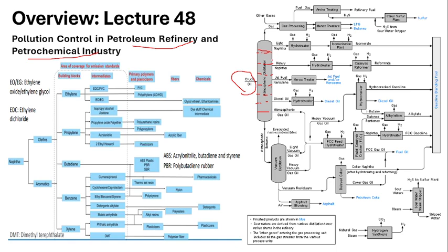First, take the first output, light naphtha. It is subjected to hydrotreating, which uses hydrogen gas to remove the sulfur from the naphtha molecules. Okay. So sulfur is removed from the naphtha, and then this treated light naphtha is subjected to the isomerization plant.